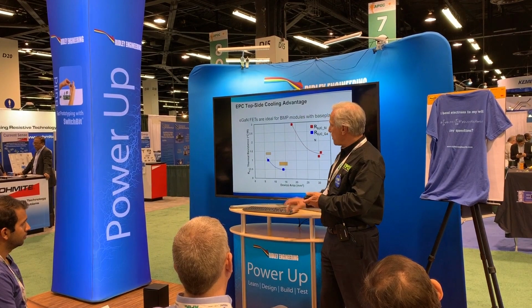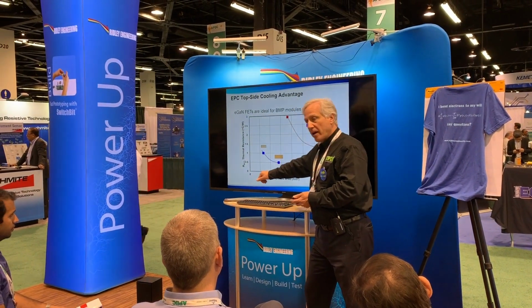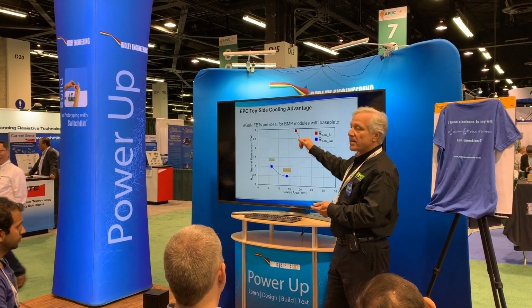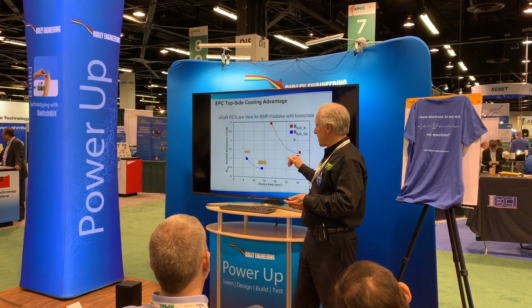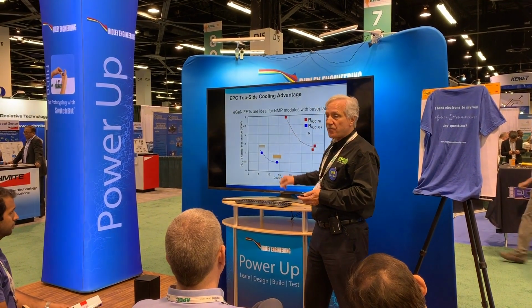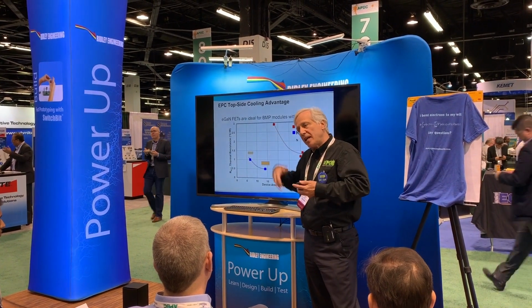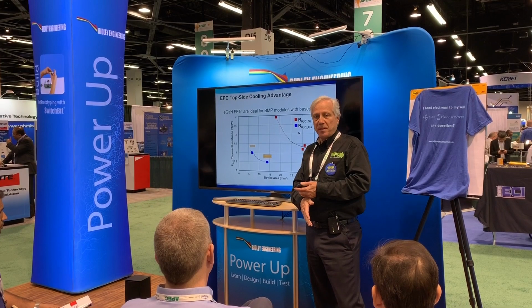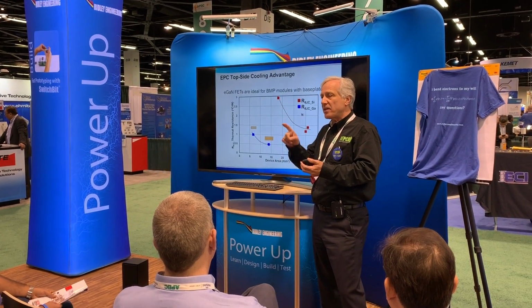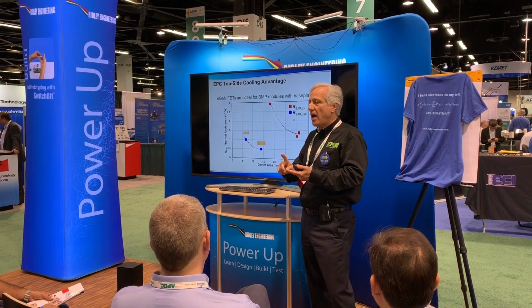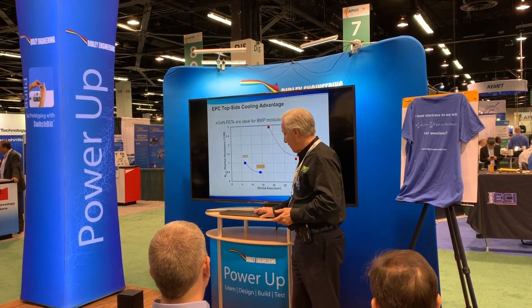So this is showing you the thermal resistance junction to case, comparing against, once again, the DirectFET, the most thermally efficient package. The red dots are silicon, and you can see about a 6x advantage in terms of getting the heat out through the device. If you look at heat into the PC board, that's limited by the PC board resistance. So you have a thermal advantage, an inductance advantage, a capacitance advantage, and a die size advantage, right? I said there were more than that, right?